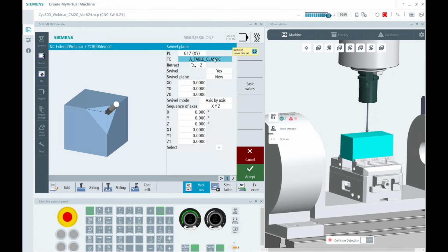But this activates the dynamic fixture offset functions. This activates what we call our tool carrier. The retract method, this is going to give me an opportunity to get the head up out of the way before the rotary swings. And what ones you have here is really dependent on the OEM when you commission the machine. Generally speaking, I would always expect to at least have the Z retract, and this is going to go usually to the extent of the travel in Z. The ZXY will move straight up in Z first. That's where there's a space between the Z and the XY, and then move the XY simultaneously to a safe position before anything spins. Then you can do like a little retract one. This is good if you use the tracking function.